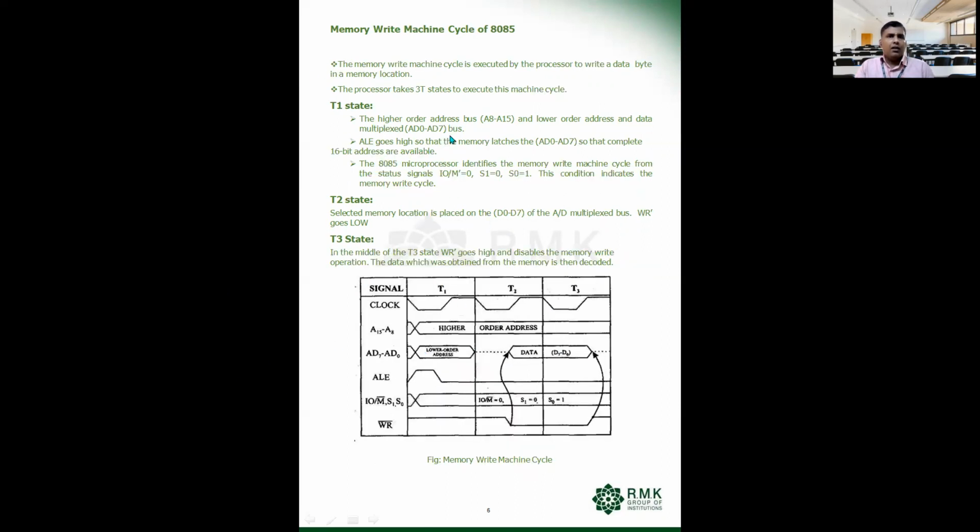And similarly for the memory write operation, it works the same way, but the only difference is that it is going to have a different status signal as well as the write signal. So it is also 3 T states, T1, T2, T3, which is 3 clock periods.